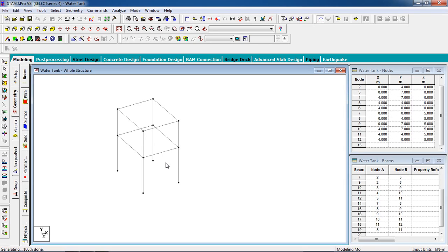Okay, if you want to give some height to the tank, you can give it. Okay, for that you have to add the beam onto columns, because if the height is maximum, then there will be live load, dead load, and also wind load and seismic load.